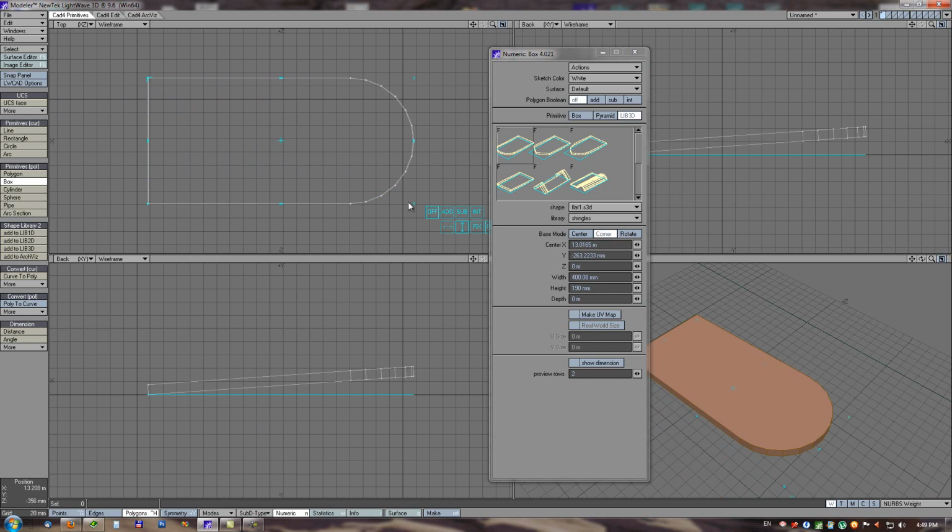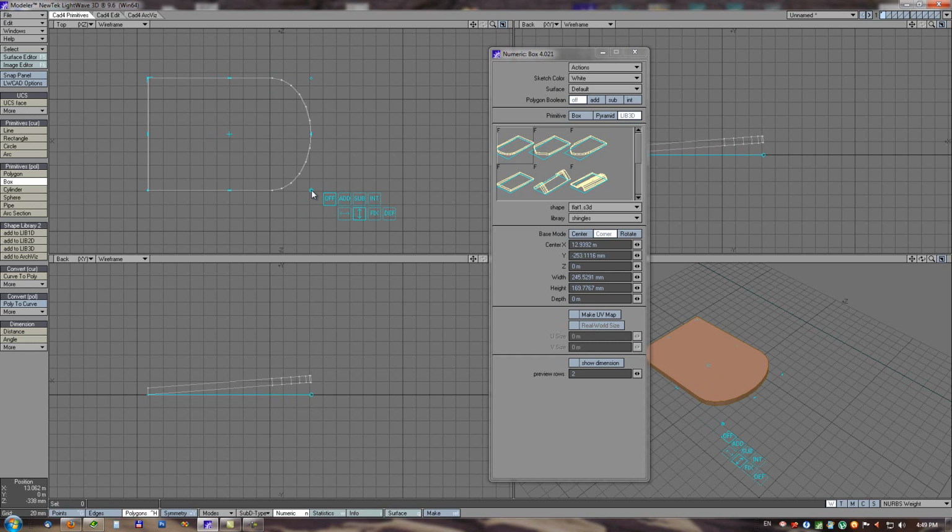And for shapes, the 2D button is useful because when we are in 2D mode with this tool, the shape is always properly scaled. The height, or in this case the depth, of the 3D shape is always properly scaled. It is calculated from the base dimensions, width and height, according to the ratio in which the shape was stored in the shape library.